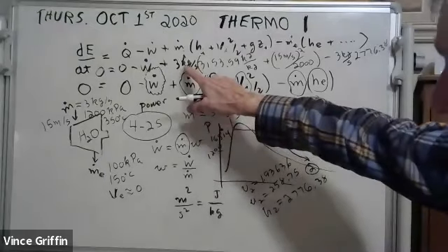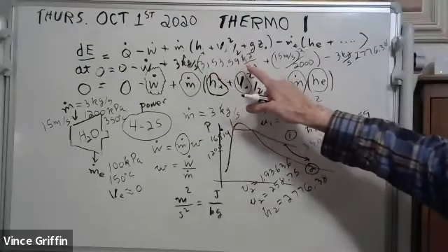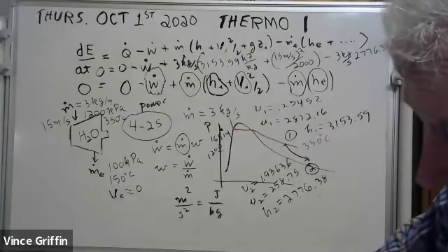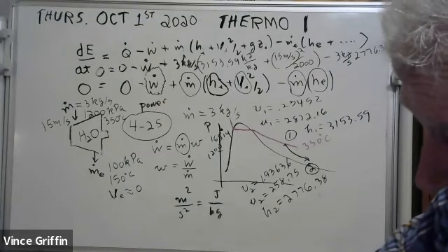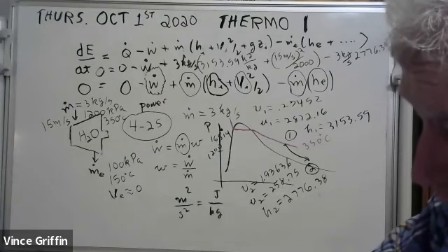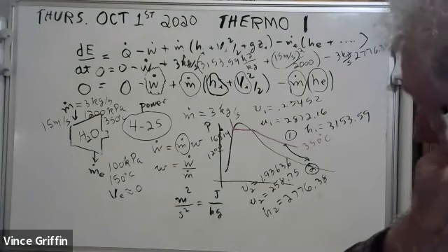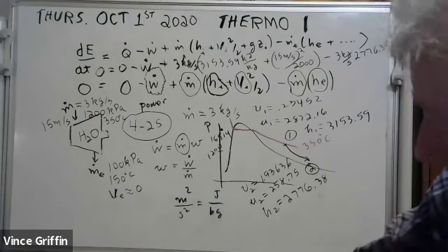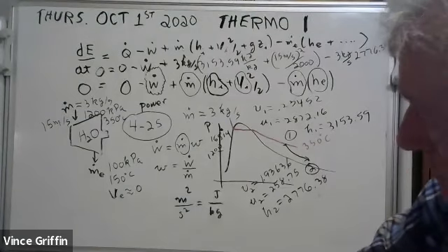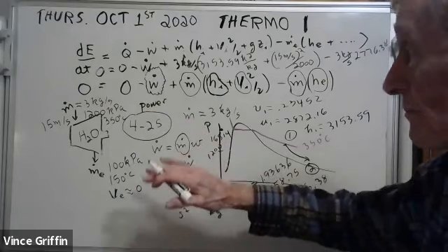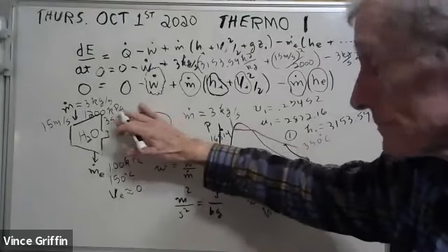Think about it. If you have kilograms per second times kilojoules per kilogram, you get kilojoules per second. You know what that is? That's a kilowatt, isn't it? A kilojoule per second is a kilowatt. So I think I have the power. Let me tell you what I got.